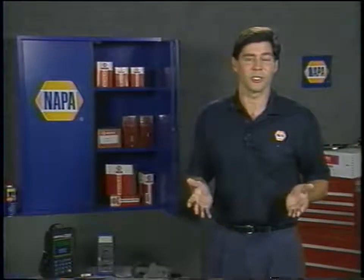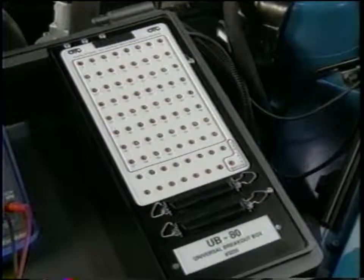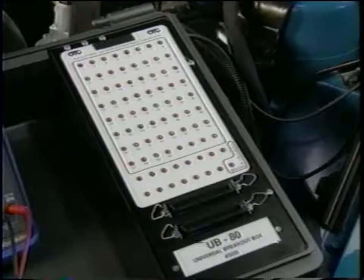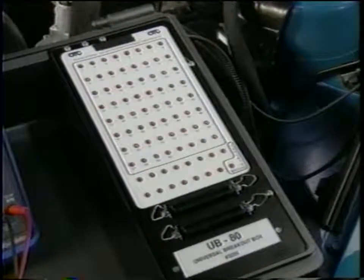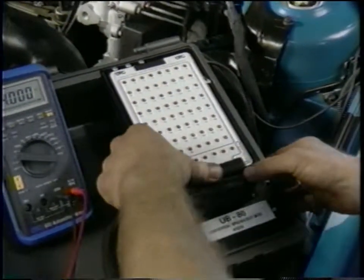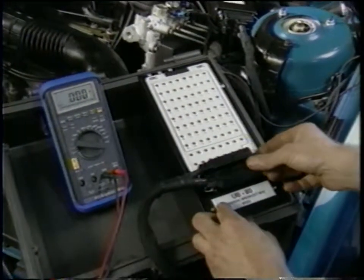It's also better than an analog volt-ohm meter, because a 10 mega-ohm impedance digital volt-ohm meter provides a certain amount of protection against overloading sensitive electronic circuits, which can be damaged by test meters that lack the proper impedance. Another piece of test equipment that's essential for ABS diagnostic work is a breakout or pinout box. With the appropriate adapters, a breakout box can be plugged into the ABS control module wiring harness to provide easy access to all of the system circuits.